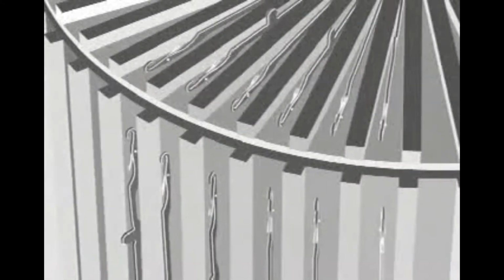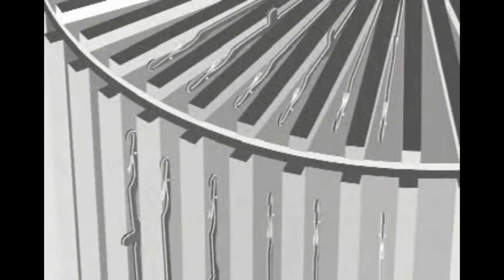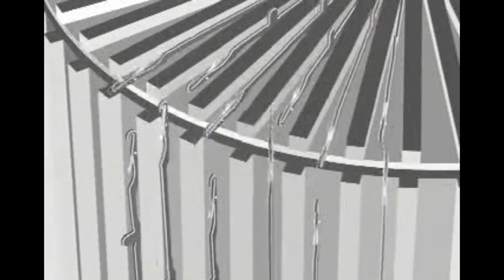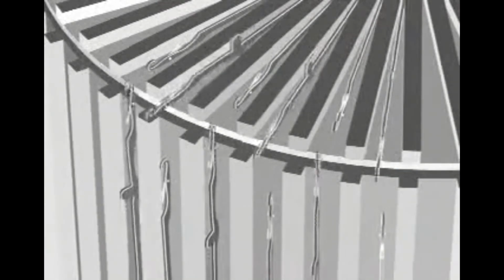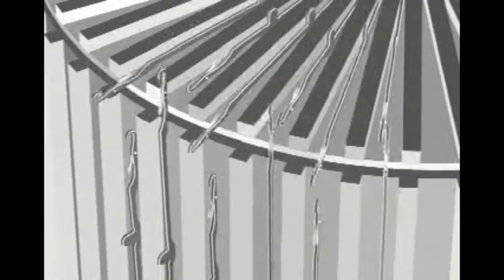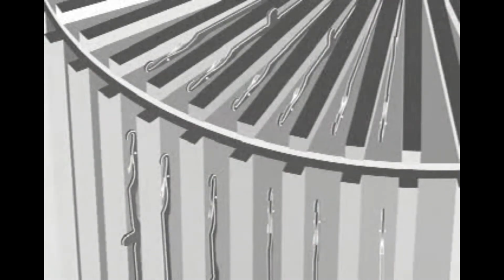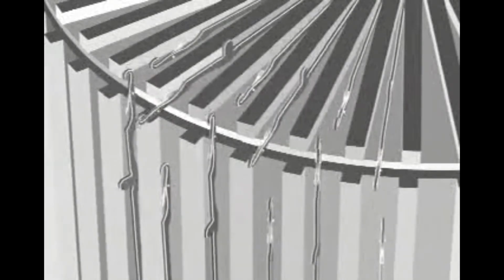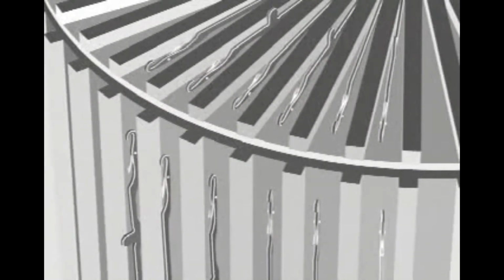In interlock gating, cylinder and dial needles are spaced so they're directly opposed. To prevent needles from hitting each other during the knitting cycle, opposing needles are not selected at the same time. When needle 1 in the cylinder is knitting, the corresponding needle 1 in the dial must rest. This is achieved by the alternating needles in the dial and the cylinder never being activated at the same time. This requires 2 cam tracks for both needle beds. Therefore, the location of the butts on the needle shank must be in 2 positions.